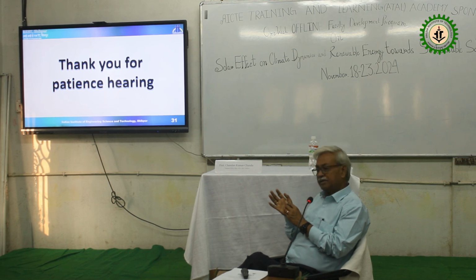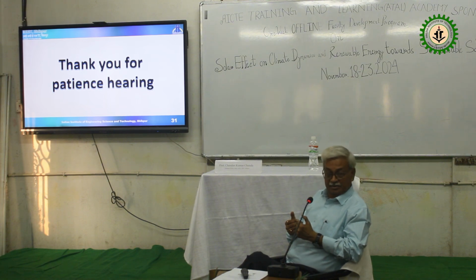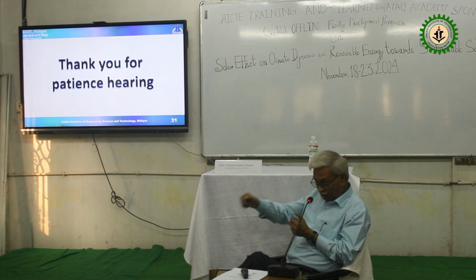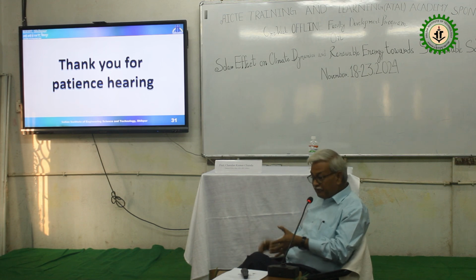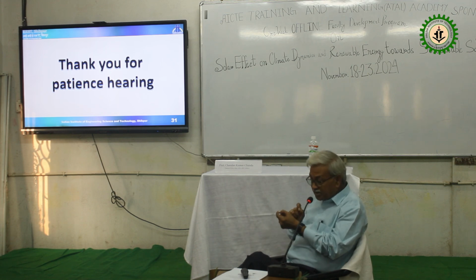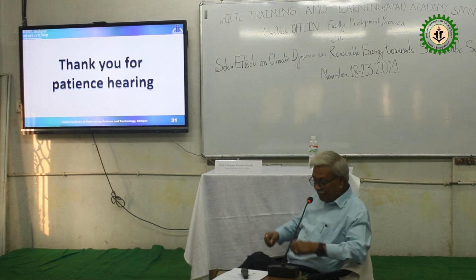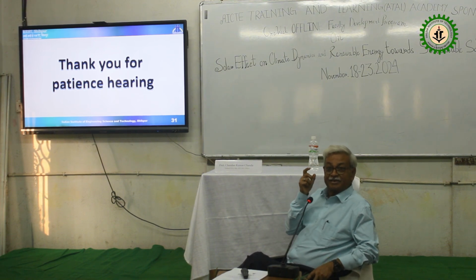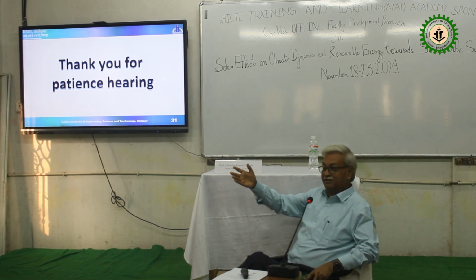Virtual inertia is basically a storage kind of device. Suddenly load demand is here. Turbine cannot generate. We cannot ask the sun or wind, you blow now, you give the energy. We cannot dictate to sun and wind. If we are having storage, on an instantaneous basis we have to develop the control mechanism in such a way that within a blink, we will be able to supply the fraction by millisecond, so the system will never understand that there is a deficit of power. The power will start flowing and there is no question of frequency deviation.